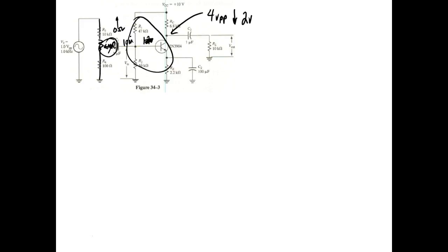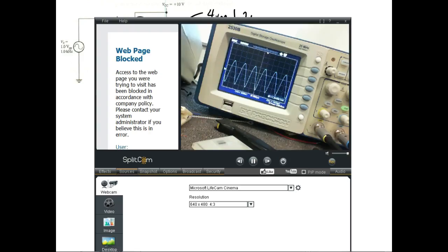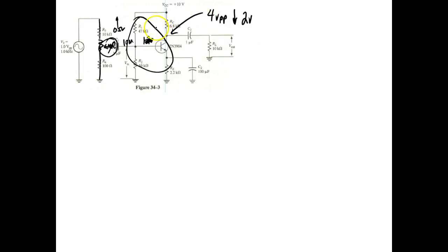So right now I have 4 volts. And I can't measure the impedance of the amplifier because it's dynamic. I'd have to turn it off. Well, if I turn it off, then I'll lose the transistor. The transistor's not even in play anymore, right? You understand? I can't put my ohm meter into a circuit with power applied.